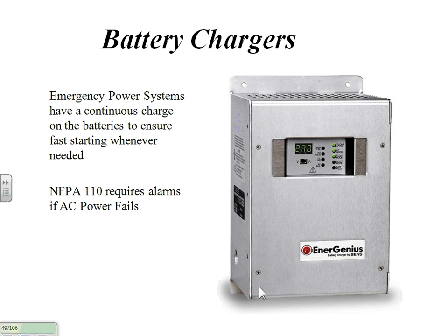Battery chargers. Interstate has gone to this brand. This is a Sense charger that they make for us. This particular model is called the InterGenius. The reason we like them, you see the flanges at the top here for mounting and so on, and the digital control. What used to happen in the old days for generator sets is the battery chargers had the old analog meters on them, and you'd get to the job site and the needles would be laying in the bottom of the meters because it vibrated so much. So we couldn't really put them on the sets. These are a lot more durable, and we will mount them on the sets.